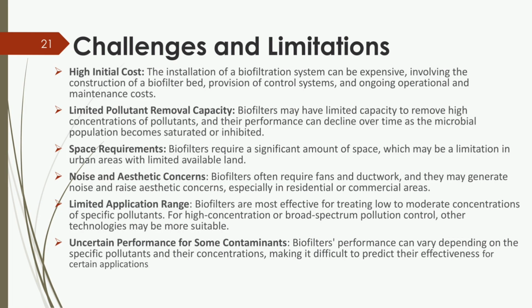Challenges and limitations. High initial cost. The installation of a biofiltration system can be expensive, involving the construction of a biofilter bed, provision of a control system, and ongoing operational and maintenance costs. Limited pollutant removal capacity. Biofilters may have limited capacity to remove high concentrations of pollutants, and their performance can decline over time as the microbial population becomes saturated or inhibited.